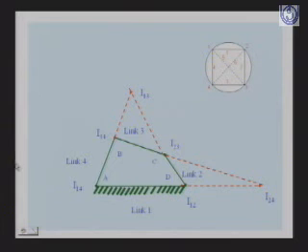Now you have to determine the instantaneous centers 1, 3 and 2, 4. So 1, 3 lies between instantaneous centers 1, 2 and 2, 3 and 1, 4 and 3, 4. So when you extend the line joining instantaneous centers 1, 2 and 2, 3, so this is your point 1, 2 and 2, 3, you have to extend this line.